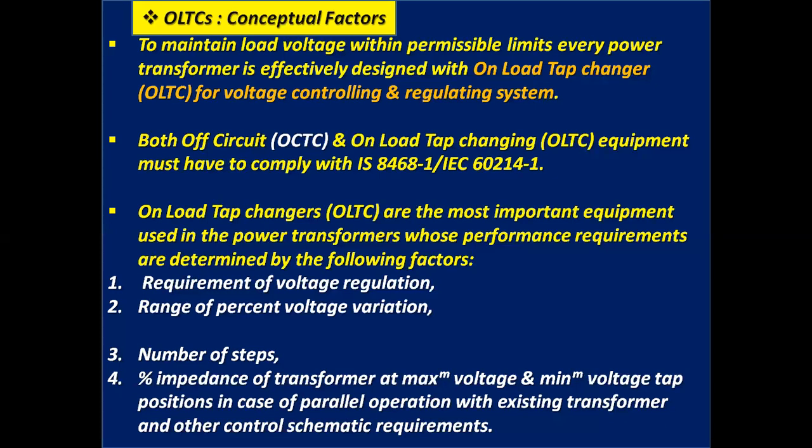certain factors. One, requirement of voltage regulation, range of percent voltage variation, number of steps, percentage impedance of transformer at maximum voltage and minimum voltage tap positions in case of parallel operation with existing transformer, and other control schematic requirements.